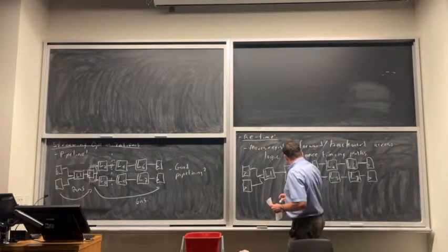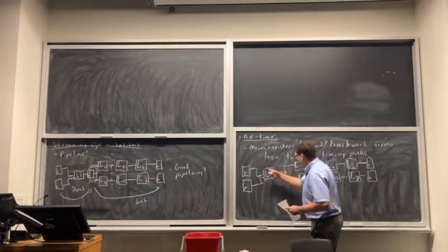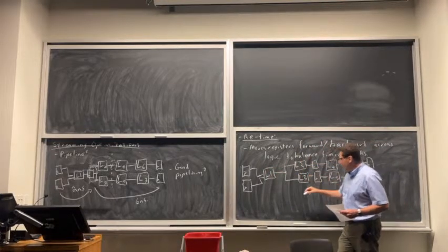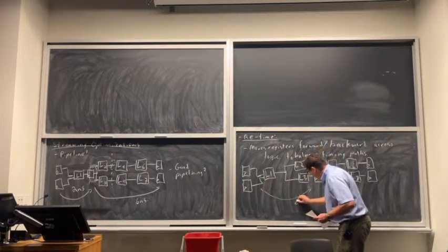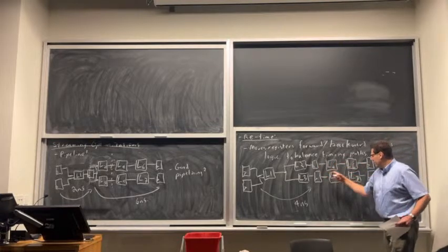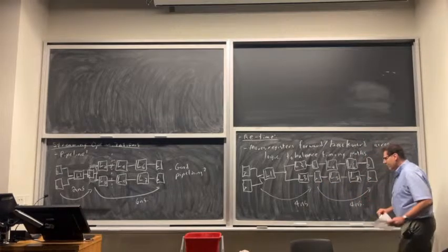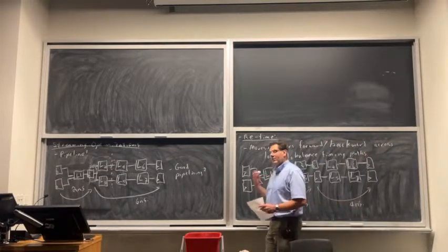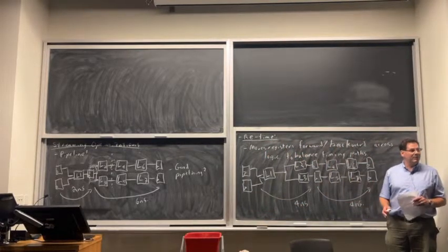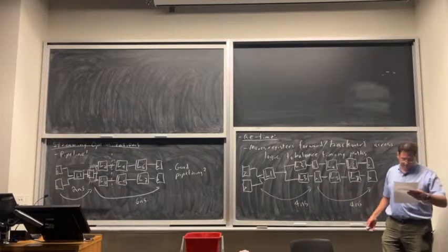Okay, so if these are LUTs plus the routing of its output takes 2 nanoseconds, that's 2 nanoseconds, 4 nanoseconds to this register, 2 nanoseconds, 4 nanoseconds to that register. So for those timing paths, they're 4 nanoseconds long. And from this register, 2, 4, from this register, 2, 4. So these paths are also 4 nanoseconds long. Now my clock frequency, I can clock this as fast as 4 nanoseconds, which is 250 megahertz. So it's also a nicer number to invert, it's an extra bonus. So it's a significant speed up, okay?